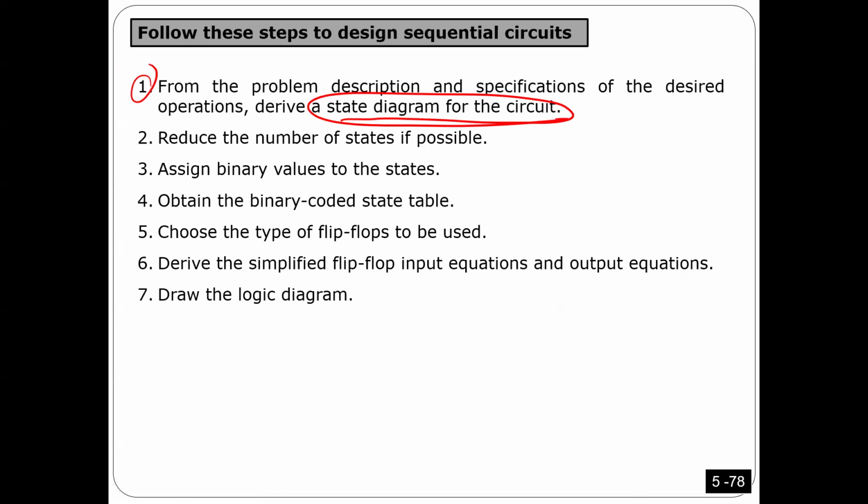So from the problem, or from what you want to design, for sure I will teach you more details. The first thing you have to do is draw a state diagram, and that can do whatever you want to do. Okay, I want to design a circuit that's doing something. The first step I have to do is draw the state diagram. This is number one. So this state diagram has to do exactly what I want to do. This is usually the most difficult part.